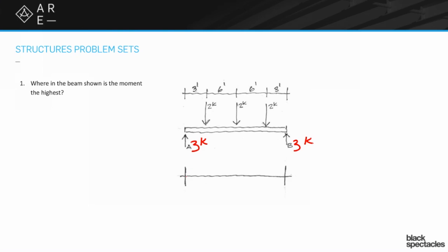Now, if you feel comfortable going intuition-wise and keep going that way, you will ultimately come to the answer that the moment is highest right here at midspan. But for those of you that don't feel comfortable doing it that way and want to do a little bit of the math behind it, we're going to show you how you can get there. The thing that'll get us there is we're going to draw the shear diagram for this beam, where I've always been curious why you use V for shear, but that's one of those engineer speak things.